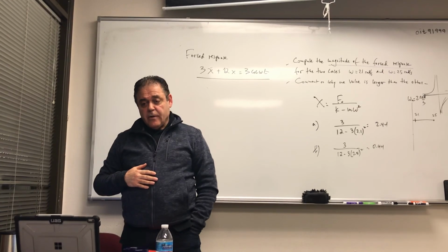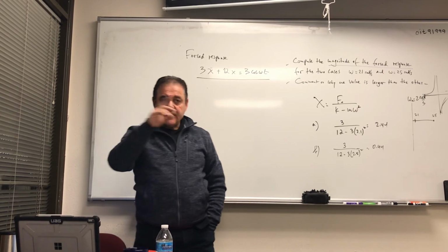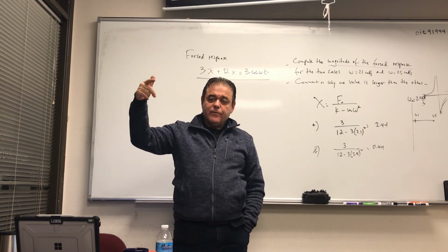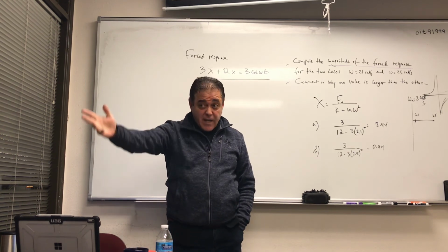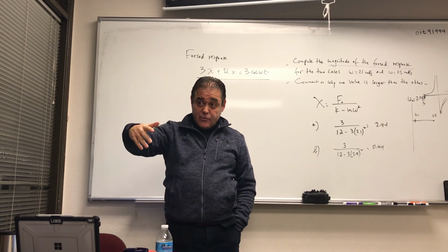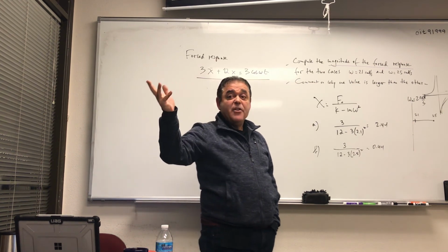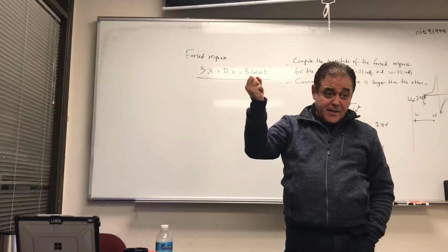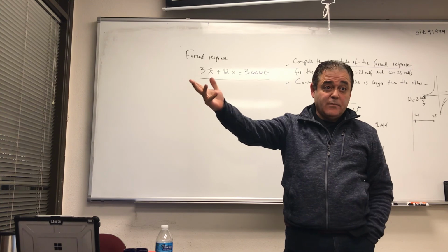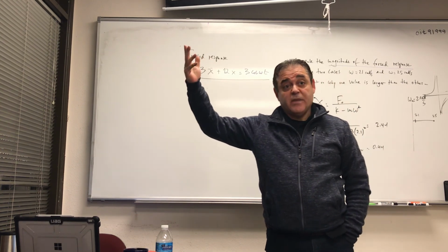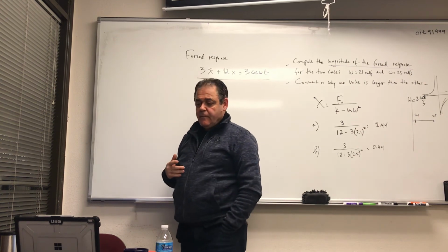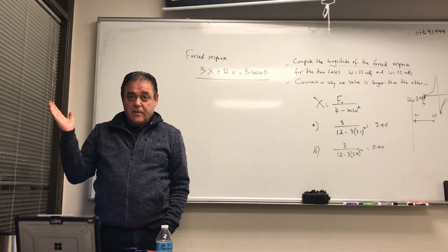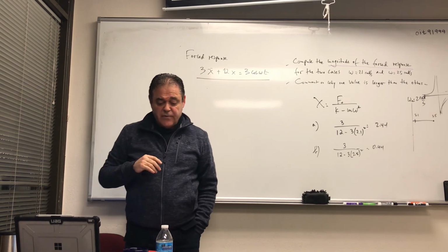And then in chapter 3, aside from the issue that omega n is equal to the square root of k over m, sometimes when you change k or when you change m, how does it affect the natural frequency, and be able to find some unknown stuff. Like earlier, we had an m and k, and then we changed just the k, and based on the change in natural frequency, you're asked to find what is the mass, or what is the k of the system. The only equation we used for that one is the equation for natural frequency, and be able to manipulate that equation to find that.